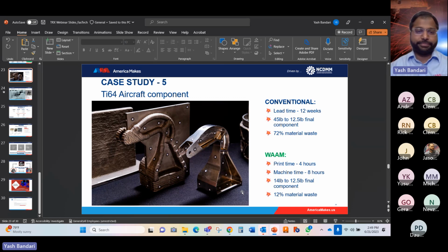And then in terms of monitoring, there are at least 4 to 5 main building process parameters that we monitor. We monitor the wire feed speed, travel speed, and then the current and voltage for the WAM process, and the argon content, all of those things, which are very important. Of course, other secondary parameters as well. But I think all these things put together will be helpful if we were to go and do reverse engineering. If there is any anomaly that we see at the end of the printing process, now we have some data to say that, okay, this has gone wrong, and that is the result of this. So, from a qualification standpoint, to increase the TRL levels, monitoring is a major point that needs to be considered for printing the parts.